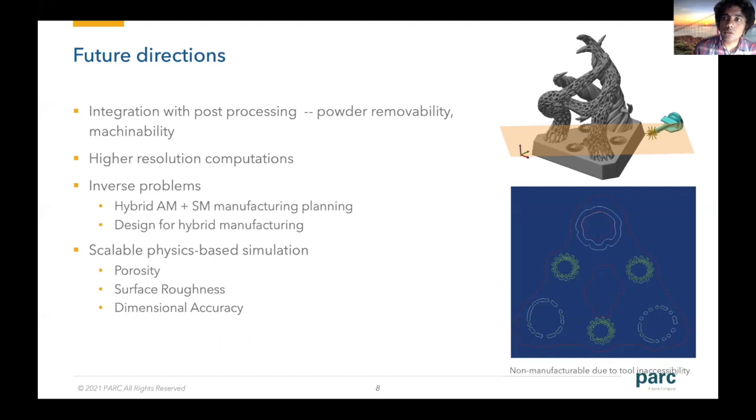Yeah, good question. The goal is to minimize any kind of change you make to the geometry, so you want to retain the design geometry as much as possible. I think of it as basically a material addition process that can be undone. If you add some extra material because of additive manufacturing, making sure the walls are thick and things like that, you also want to make sure that the way you're adding the material is done in such a way that you can eventually take it out later with the machining tool, right? And that raises a lot of challenges.